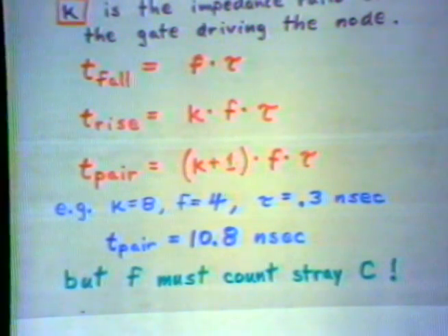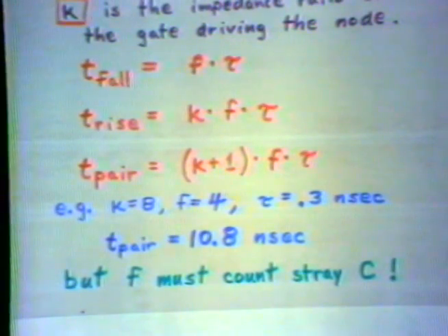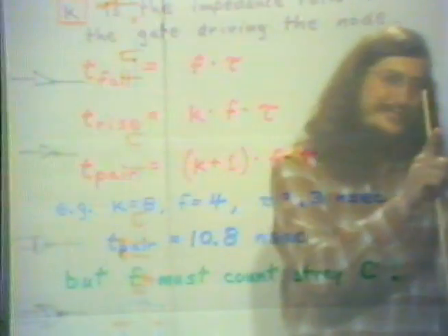I think typically areas of wires count about 1 order of magnitude less than the area of the gate of a transistor. So if you go that far on a chip, you can drive a device about that big without worrying too much about counting the stray capacitance. Scale that down a little. Okay. So you can do reasonably long interconnect without worrying about the strays.